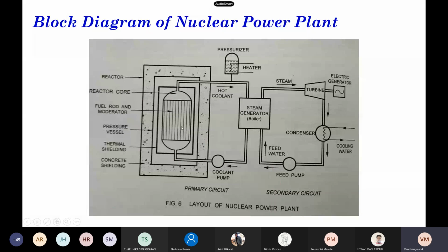Once it is elevated to steam, it will lead to adverse happenings, disruption of the safe working of the reactor, and even burnout of the nuclear fuel element. And whenever the pressure decreases, it causes cavitation, which is again harmful.